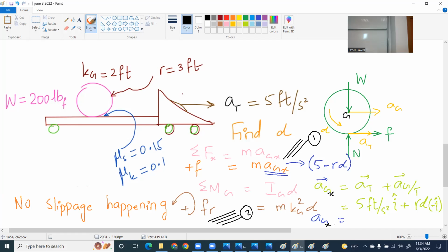You remember midterm exam 1, omega square R used to give you a J component. I don't care. I'm concerned about the X. AG with respect to T means those big terms. Remember? R alpha, omega square R, 2 omega cross V, AG with respect to T, small xyz. Those big terms constitute AG with respect to T.